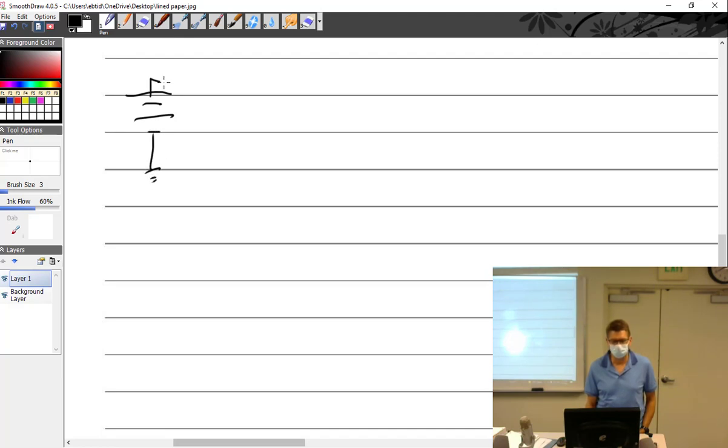So if in reality, off the battery, you have a bus. And honestly, in most planes, it's just a thin strip of aluminum. And off of the bus, you tie the circuit breakers right off that bus. So there'll be a whole row of them like that, circuit breakers. And then from the circuit breakers, you'd usually have a very short piece of wire, very short, going to the switch.